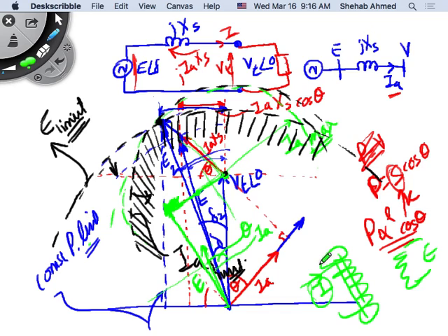At some point, theoretically, you don't need any more current in the field winding to be able to have voltage on the terminals of the generator because of all the reactive power. Remember, reactive power, capacitors, what do they do? They change the voltage. How? They supply the reactive power locally to the load, meaning there's no voltage drop anymore across the line. So if the voltage was low, it actually increased the voltage because there's no voltage drop anymore.